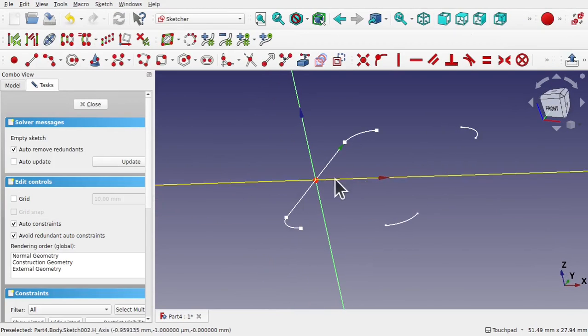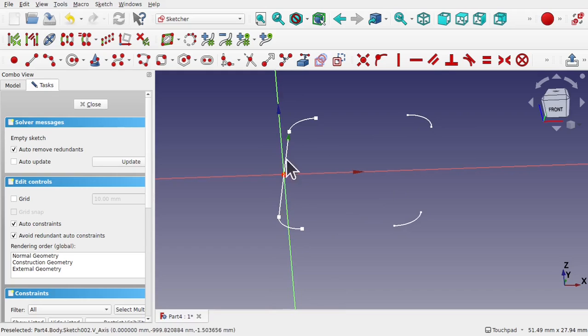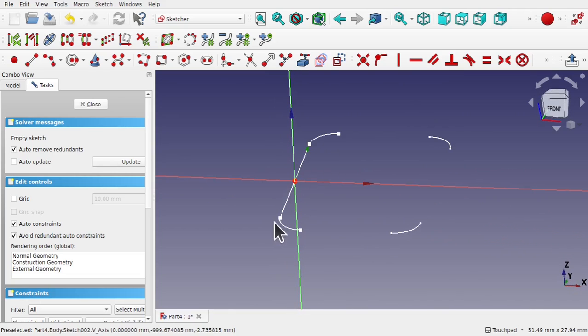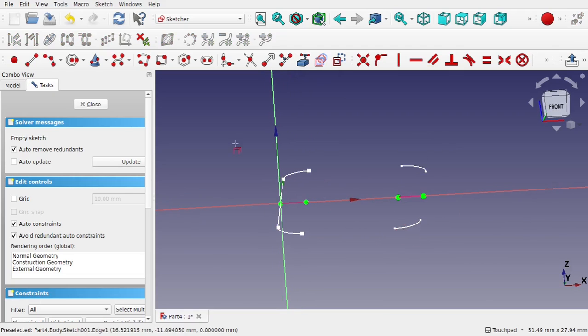It's placed us in the center of our scene. So in the center of this line here, which is fine because we just changed this via offset or attachment. I'm going to pull in these arcs and they will create a planar geometry along that line. So using the external geometry tool, pull in both these arcs. Now what we can do is create an endpoint and endpoint arc. Remember, we've got the auto constraints on, and we'll hover over that point to make coincident constraint, hover over this point to make coincident constraint, and create our arc. So we've got this arc in here.